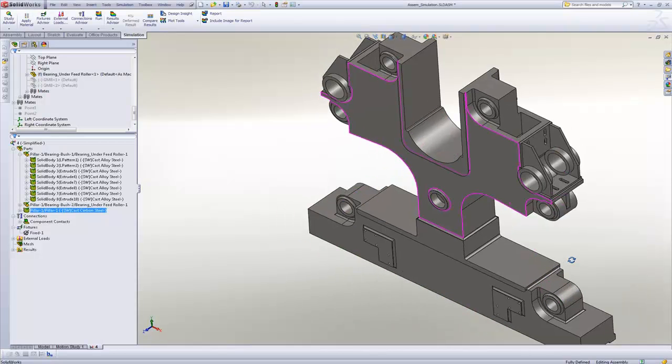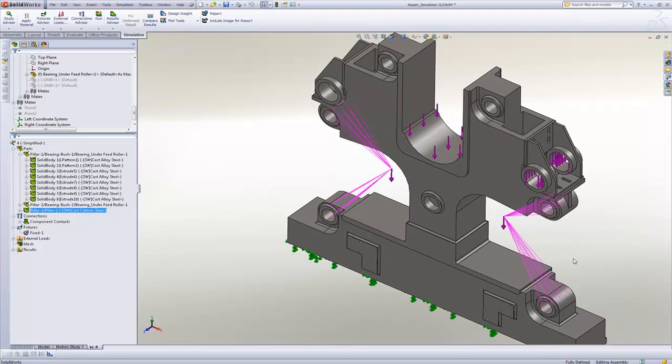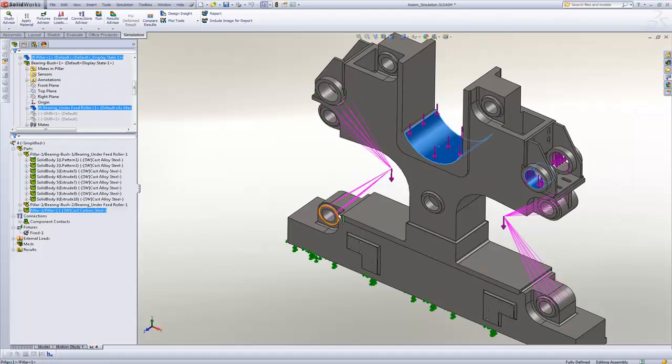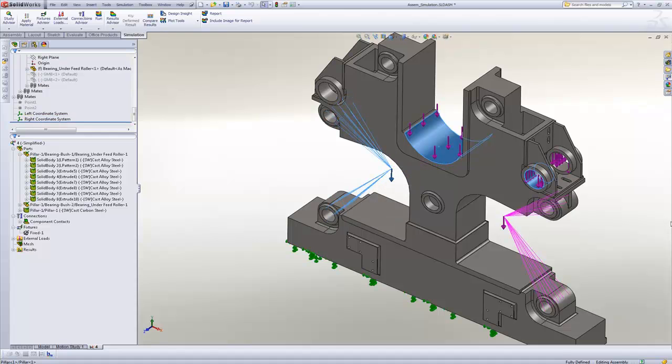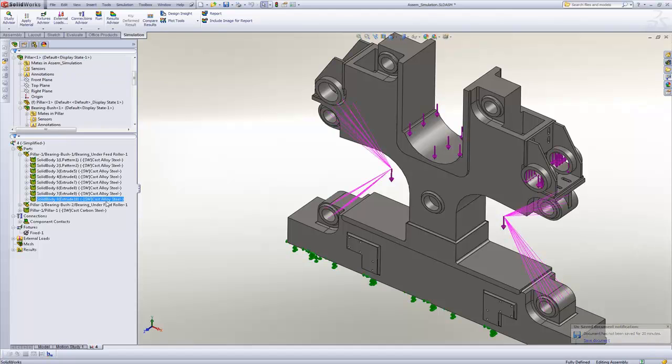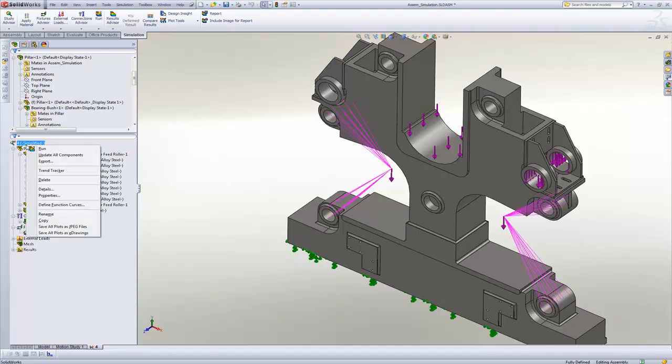It is time to validate design of the pillar subassembly which bears the entire load of the rollers. 4 rollers are heavy and directly transfer all their loads to the pillar. Pillar gets grouted onto the ground. Rollers' individual weights are considered to be acting on the respective interacting faces. Remote loads are considered for bottom rollers. Pillar and rollers are of cast alloy steel.